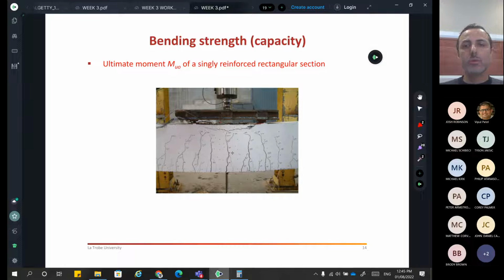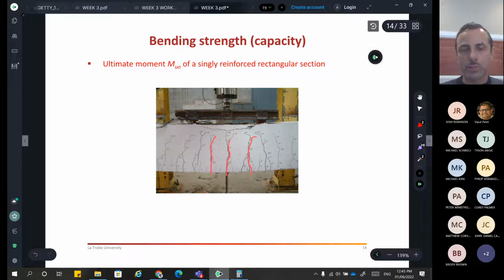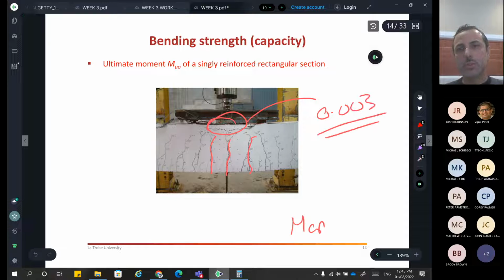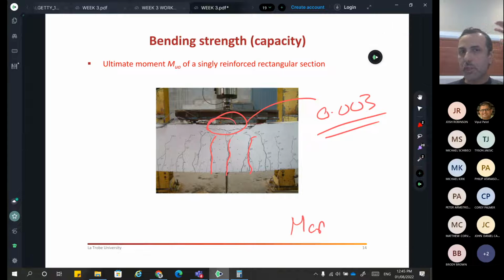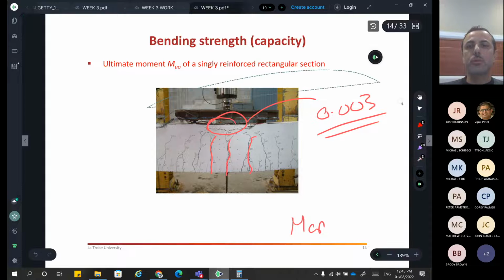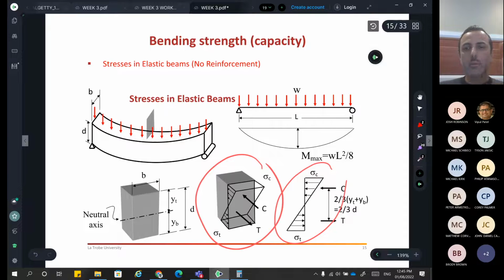So you say, these are the strength failure cracks, the micro cracks, you don't see them, and the other ones when we reach the cracking or the loading crack. When does this happen? It happens when we reach the 0.3 strain. Obviously we want to design our concrete where these failures will not happen. This is again just a recapping.